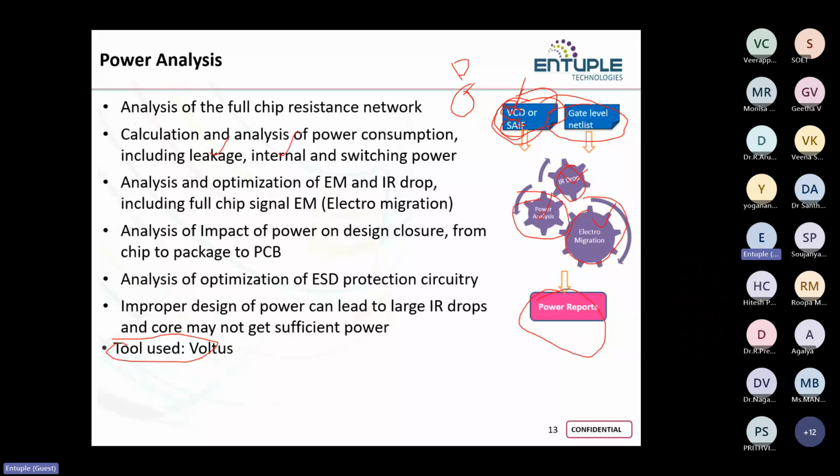If leakage is more, then you have to think about whether your power planning has to change in the physical design, or you have to go back to your clock gating or some kind of low power techniques. Also, Innovus tool has inbuilt low power techniques like clock gating, power gating and so on, so it works without designer involvement. When it is doing placement and so on, it also tries to take decisions on clock gating. It tries its level best to optimize power.